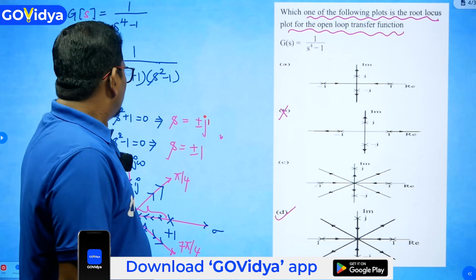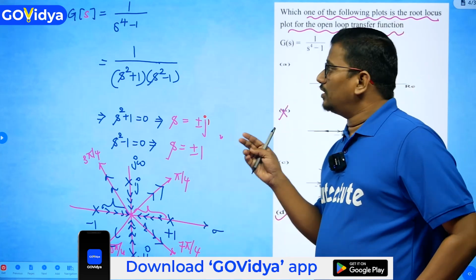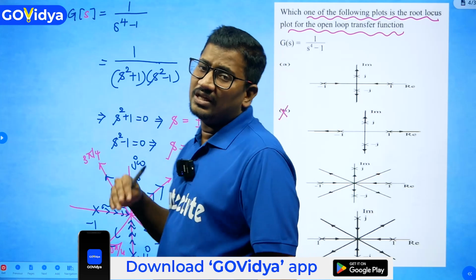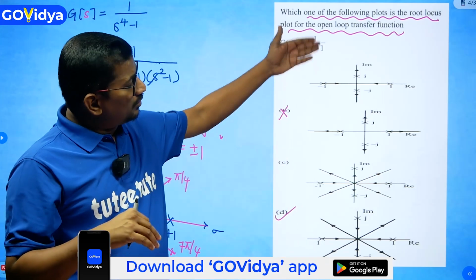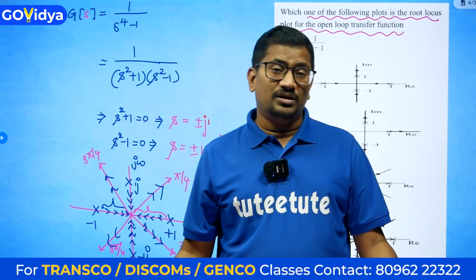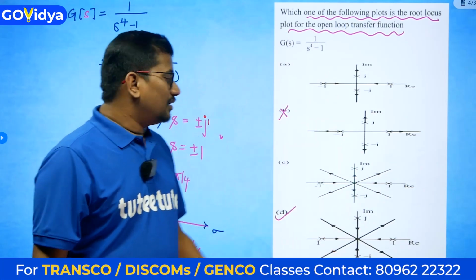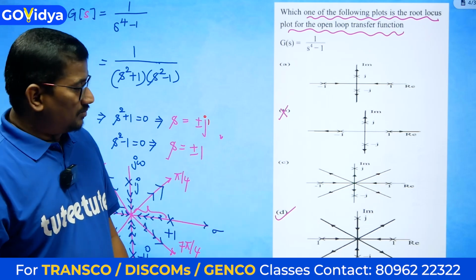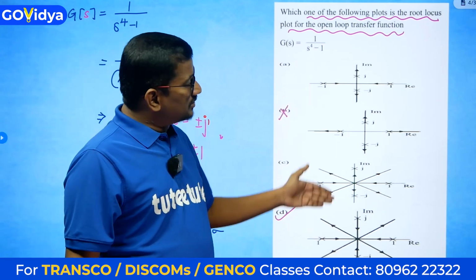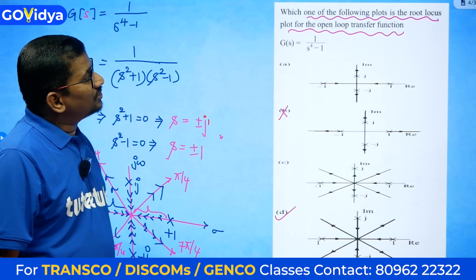Okay. So how have we solved this problem? First of all, we identified all the root locus regions and then what their pole locations are. But unfortunately, the pole locations are included in all the options. The crucial thing here is what the root locus region is, and in that region, how the poles are moving, we have to identify. As per that, we got option D as correct, because angle of asymptotes is very important here. Without that, there are 3 possibilities and you can't decide which is the correct one. Okay, so please take the solution.